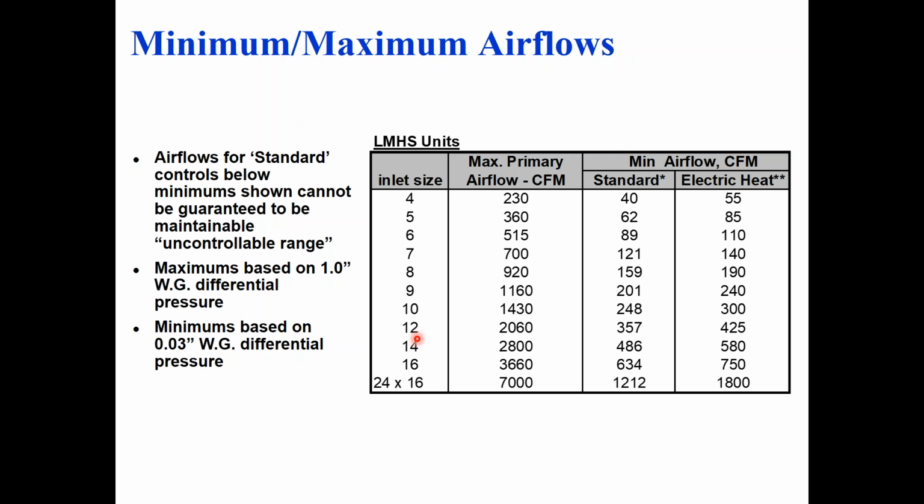And a size 7 is a size 5 is a 6-inch box with a reducing collar. A size 7 is an 8-inch box with a reducing collar. I wouldn't buy those anyway. Plus, your sheet metal guy doesn't like odd sizes typically.